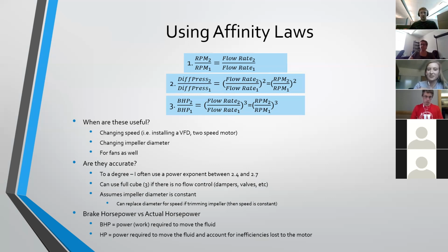Julie, I see you unmuting. Do you have a better answer? I was just going to step back and say the point of the conversation is to recognize that the affinity laws shown in your books are for the theoretical situation where there are no controls. So making a point to adjust them when you identify the controls that are in place is more of the point than the actual number itself.